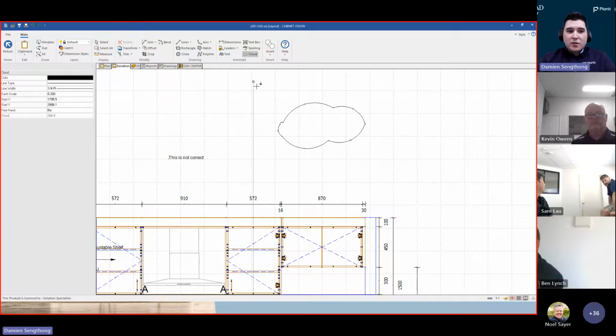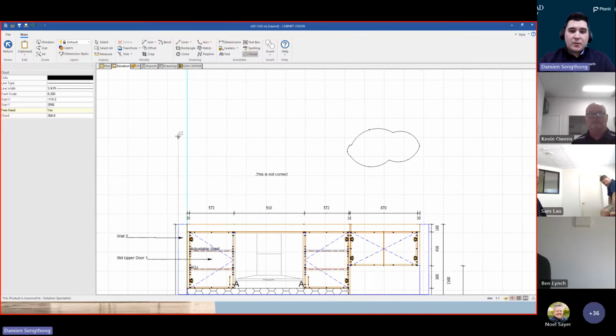So with cloud, you do have two options. You can use it by selecting the various points like I did there, or when you select cloud again under annotate, there is an option on the left for freehand. So you do not need to actually select the points. It'll just follow the shape of your mouse, or the movement of your mouse, I should say. You begin by left clicking, and then it'll follow the movement of the mouse. So I am not actually left clicking there.